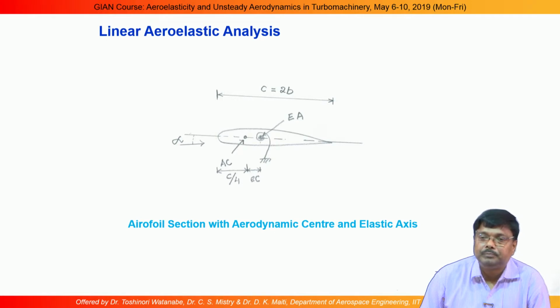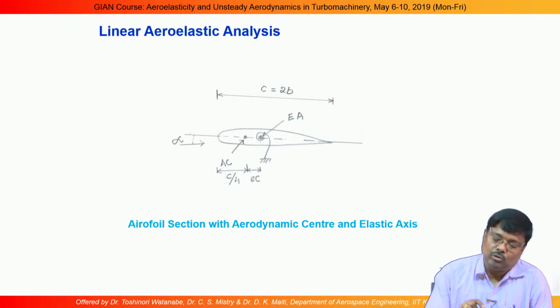So, is theta like we are taking an average at that particular spring where it is attached, or is it actually varying, and how is it varying, linearly, or is it an average? No, it is constant. It is constant about the elastic axis. The angle of attack whatever we have considered, that is about the elastic axis.